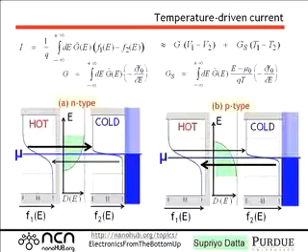That slide summarizes what I just said: you could start from that same expression and linearize it, and you'd have something depending on voltage and something depending on temperature. The first is just the conductance we have been talking about, but the other coefficient, the GS, is what will have this (E minus mu) over qT in it. And that's the standard expression for evaluating that quantity.